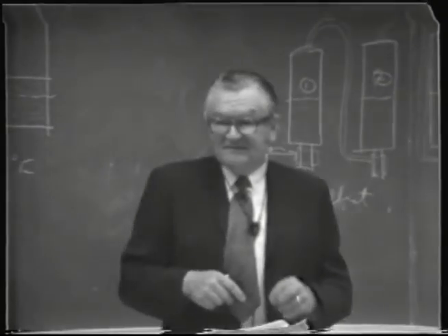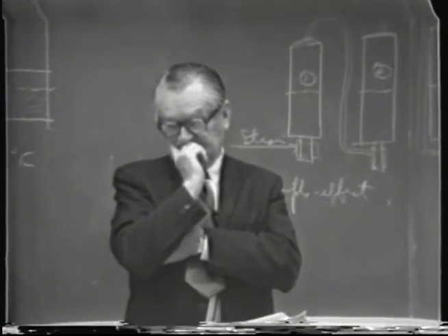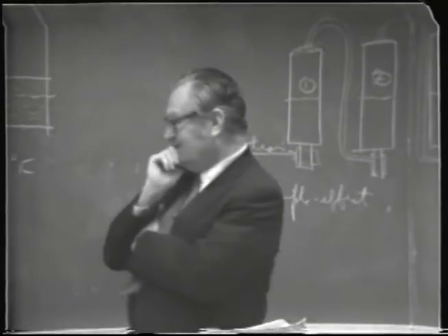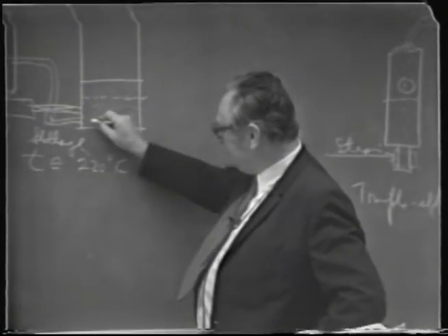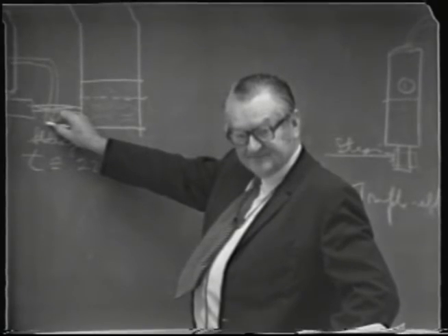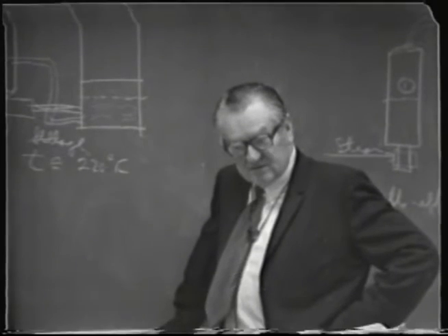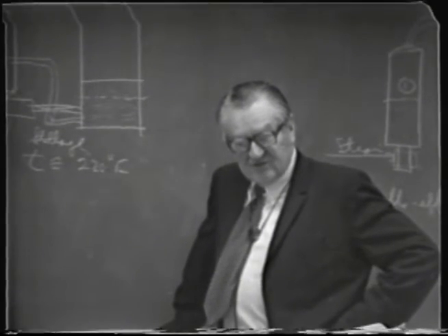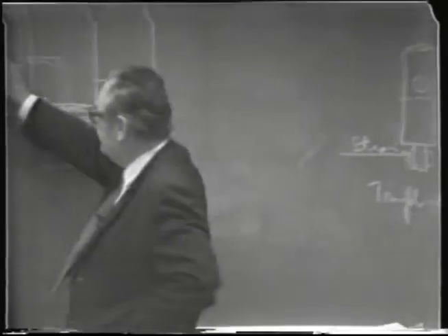Did you say you could only get energy from the liquid going to the vapor? Well, the only energy available for heat economy here is what energy is in this stillage going out. I don't see why the liquid would go into a vapor unless you could... Because you're reducing the pressure on it, it's a saturated liquid. You're reducing the pressure by bringing it into this economizer.